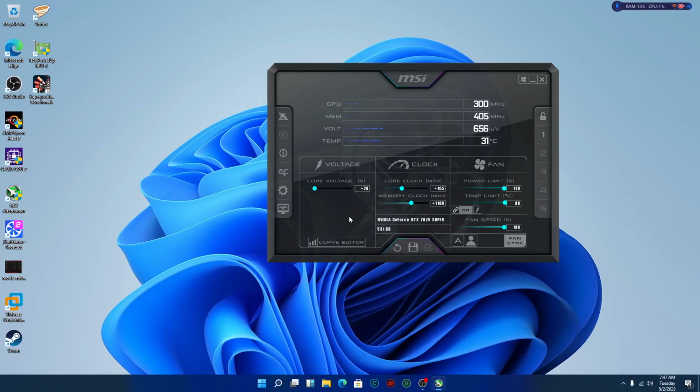And the reason I say that is because if you overclock your graphics display driver or computer, then whatever you're overclocking, you have to give it more power. It needs more power. It's going to want to draw more power, and if you don't supply it with that power and tell it to turn it up a little bit, then you're going to have an unstable computer, and your clock frequencies, your overclocking, none of it's going to work, and you'll barely be able to get any overclocking out of it.